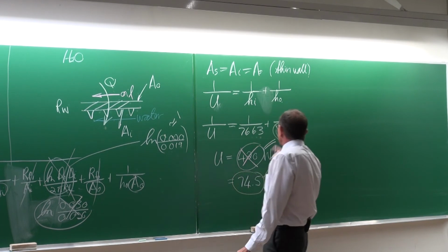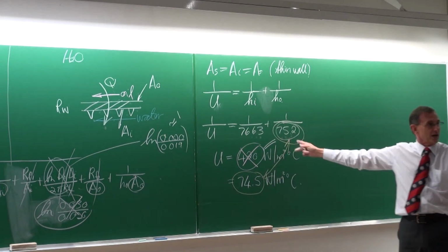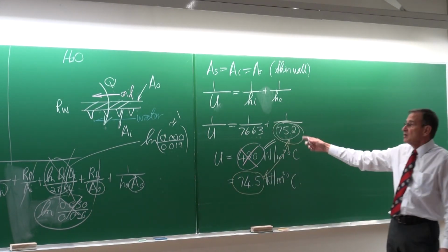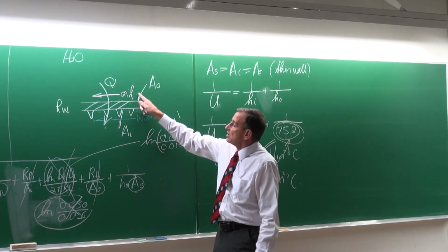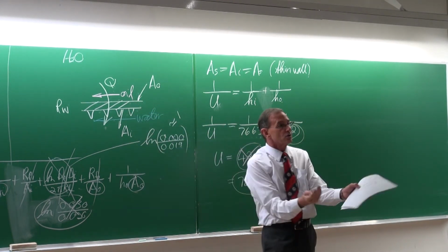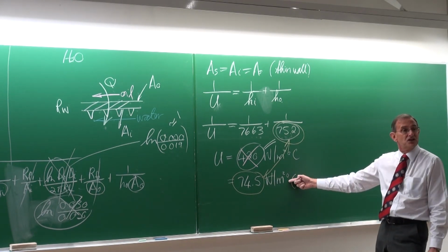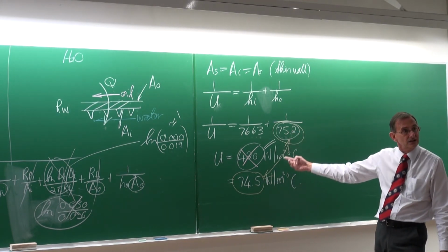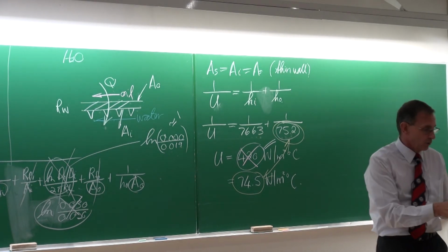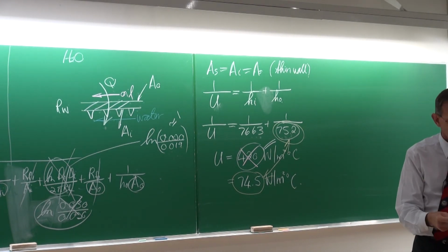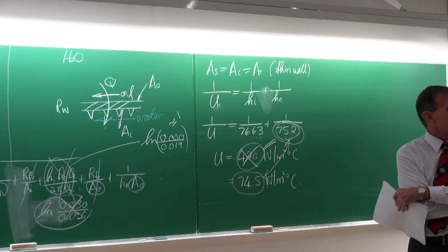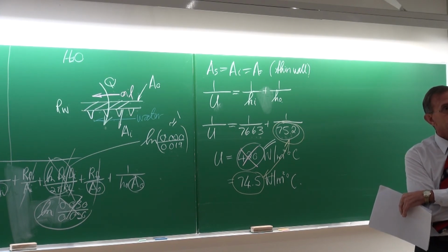Why? Because the heat transfer coefficient is an order of magnitude smaller. So if you would now go onto the oil side and you would put in some fins or enhance the heat transfer, then the heat transfer coefficient is going to improve significantly. And therefore you're going to end up with a more effective heat exchanger. Any questions? Do you understand that?